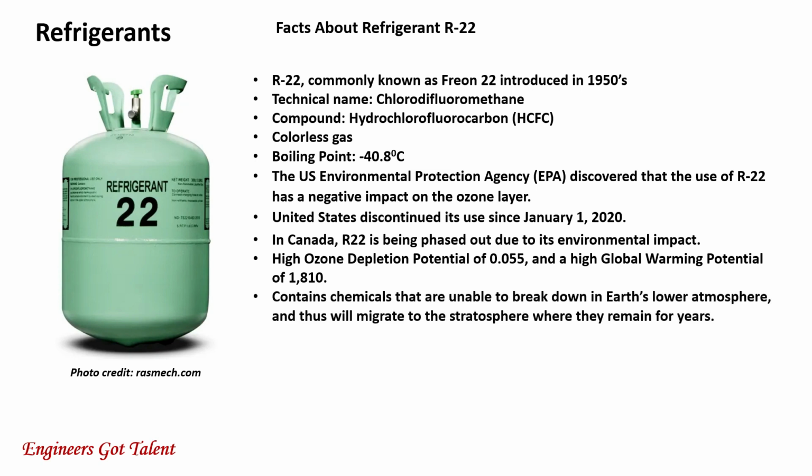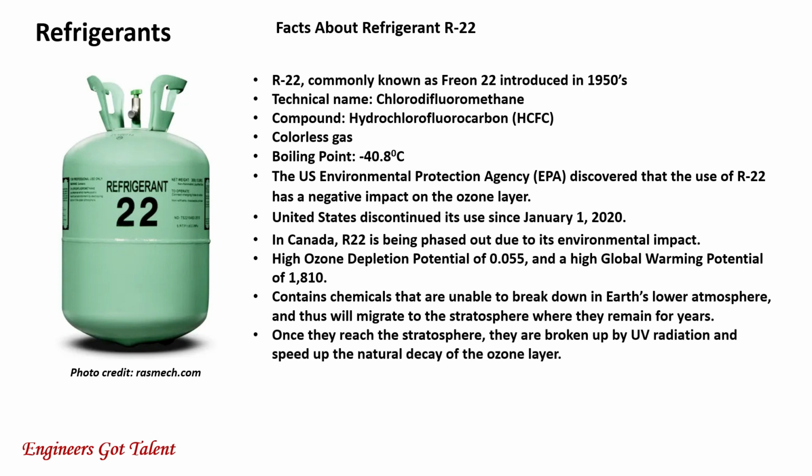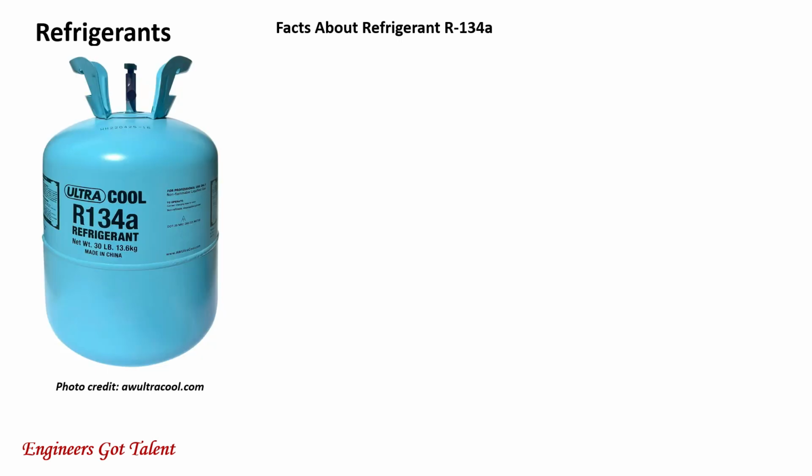It contains chemicals that are unable to break down in Earth's lower atmosphere and thus will migrate to the stratosphere where they remain for years. Once they reach the stratosphere, they are broken up by UV radiation and speed up the natural decay of the ozone layer. So refrigerant 22 is now discontinued for use. Facts about refrigerant 134A. It is also known as Freon 134A.